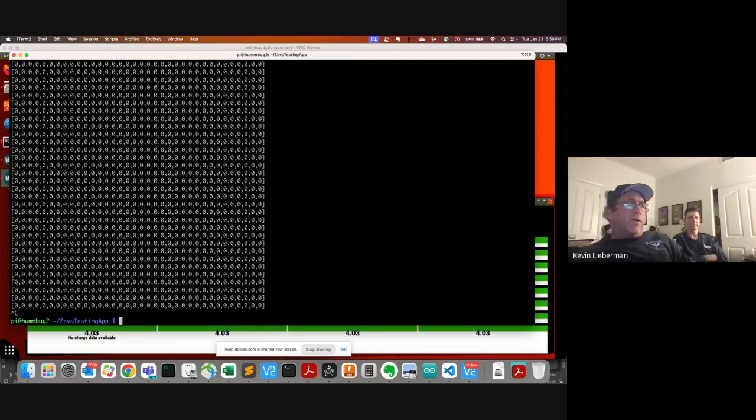Well, I just wanted to, and I'm showing the data now as I showed on the Humbug. Now I'm showing it that's coming from this little ESP32 little round display device, which is 0 because it's not hooked up to any kind of car right now. But since the data is exactly the same, I was able to make the display exactly the same. It's coming from 2 different places. So I abstracted away the CAN data, which is different between the cars, and showing it in one common place. And all this source code will be made available through the links to this video. If you want to see the code on how I did it on the ESP32, and I'll try to share the code from the Raspberry Pi version 2. I can do that here.